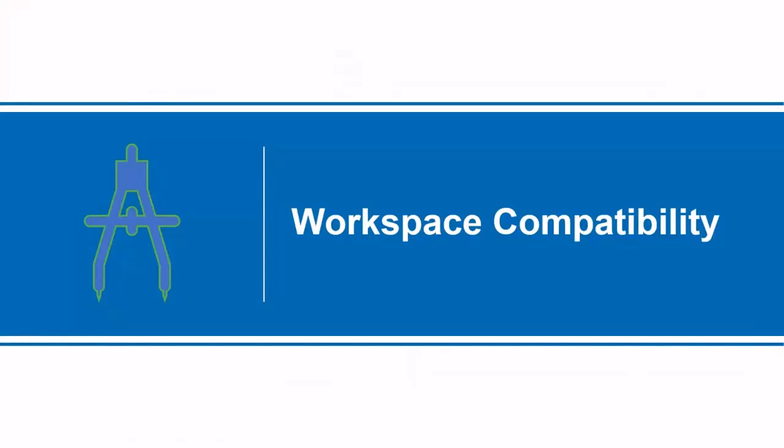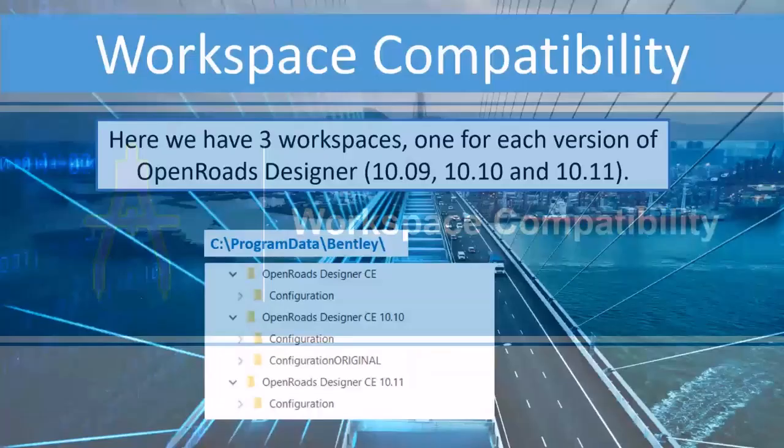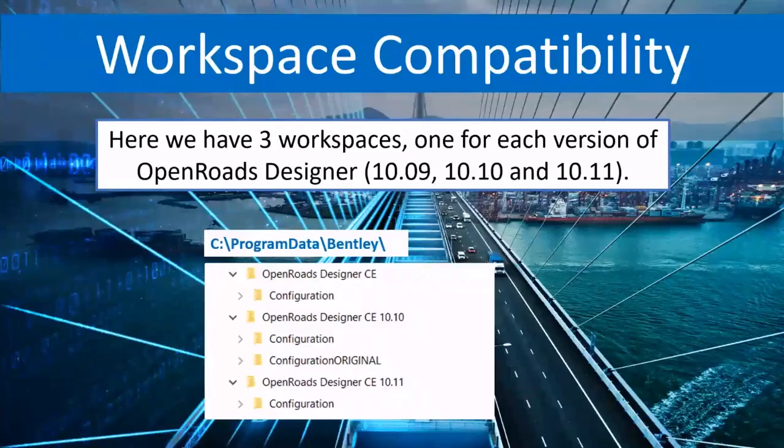Last thing here I want to share with you is workspace compatibility. Again, this is a question that we get a lot. I want to make sure everybody is clear on this. Now, you are perfectly welcome, with side by side, to have multiple workspaces running. So I showed you my machine a little earlier, where I've got OpenRoads Designer 10.9, 10.10, and 10.11 all on my machine. I also have separate workspaces for all 3 of those. If I look under my program data Bentley directory, I have a 10.9 workspace, I have a 10.10 workspace, and I have a 10.11 workspace. That's not a problem, okay, if that's what you want to do.